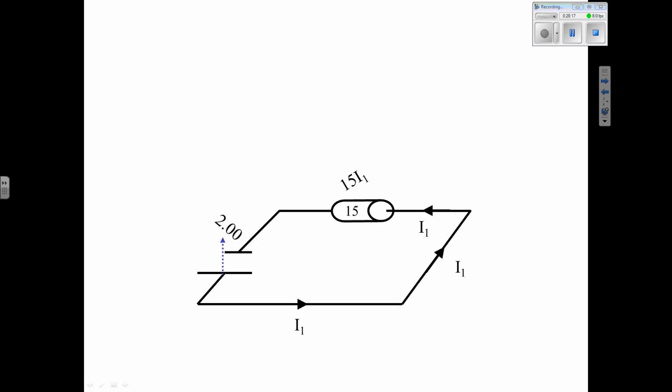So, if here's at 2 volts, and from here to the next corner, there's nothing to use up or give it energy, that means the front corner is also at 2 volts. So I draw another vertical line that's 2 volts tall from that front corner.